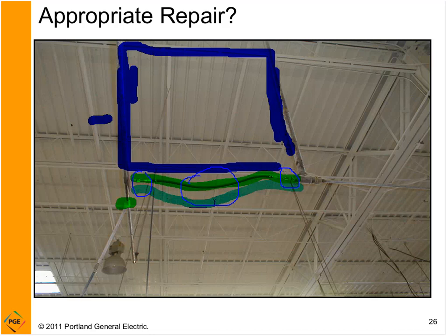Inevitably you have some end use somewhere. I know that's the ceiling, but if you have some end use and that end use is screaming, hey, I need more pressure, well, guess what? The operator goes back to the compressor room and jacks up the pressure. For every PSI, I'm spending 0.5% more energy, all because of an inadequate, under-delivered piping system.